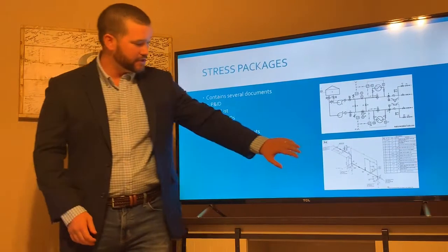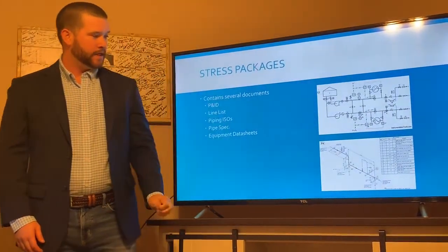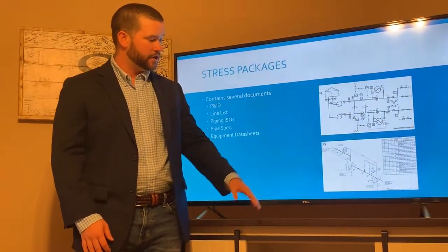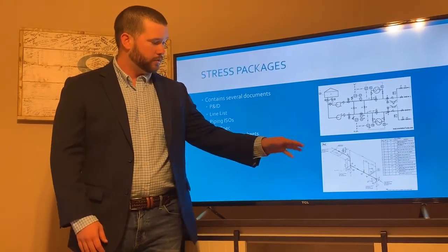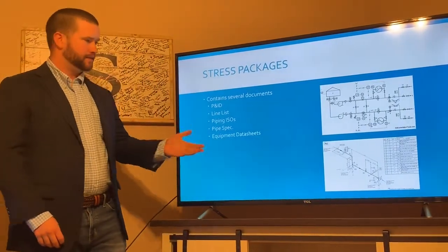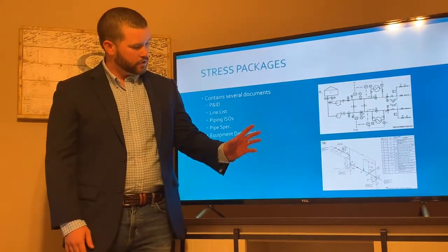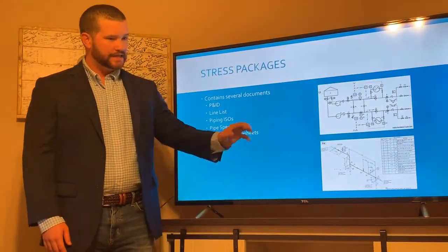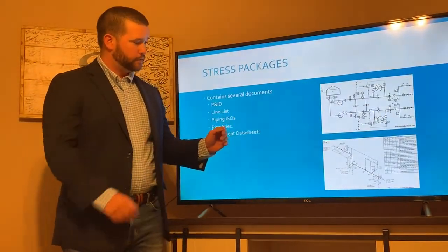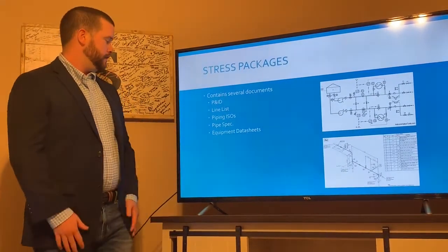In addition to just having dimensions and pipe, you also have a bill of materials on your ISO drawing, and that just has all of the materials that are contained in this drawing. You've got pipe, elbows, welds, fittings, flanges, and any other thing like that that's contained on the drawing. You're going to have it listed and itemized over on the bill of materials. And then normally on an ISO you'll have, again, process data for that specific line, and that spool of pipe is going to be listed at the bottom, so just for redundancy, you can easily find your process data.